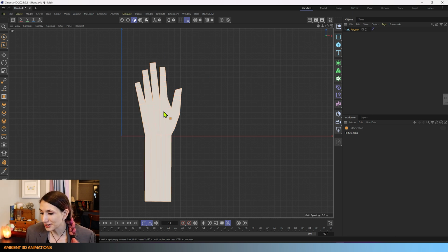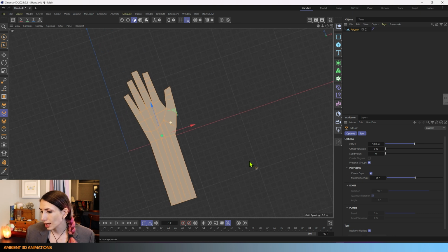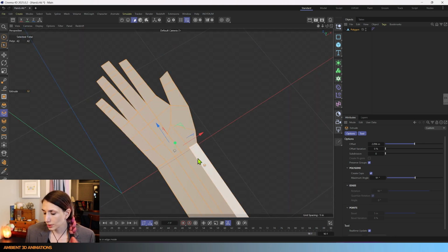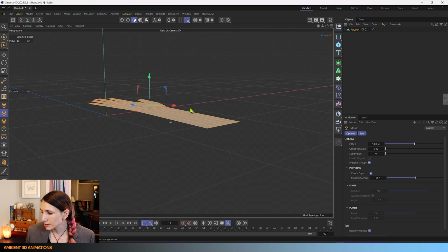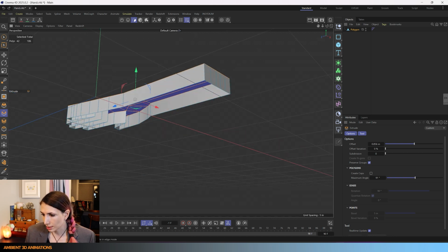We've gone over that one as well. And then we'll use MT in order to extrude. I have create caps on. I'm going to go into this perspective because this is where sometimes things go wrong. I actually might just turn off caps to see how this is looking on the other side.